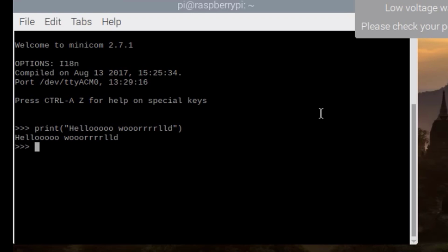But that doesn't mean we will use it like this, right? So let's first try to access the hardware also. Let's turn some LED on, the onboard LED, actually. So import the libraries: from machine import Pin. This is for the GPIOs on the board.